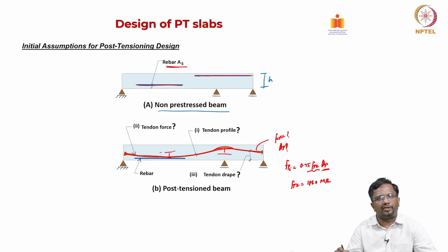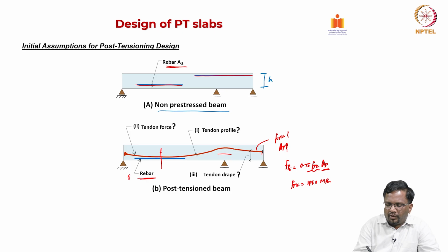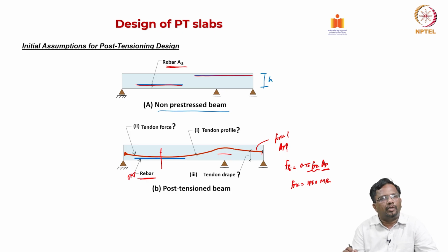So, in pre-stressing design, it is not only about the amount of pre-stressing steel, unlike RC design. Here we also look at what the cable profile should be. If at a location my bending moment demand is higher, then I can always substitute with TMT rebar to meet my strength requirement.